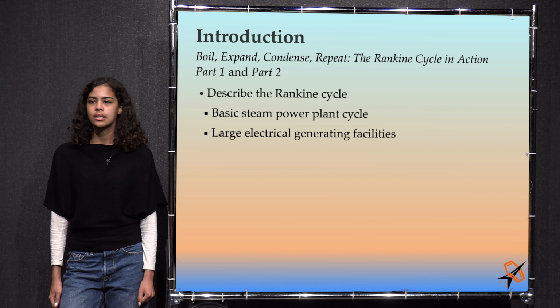We have a boiler, a turbine, a condenser, and a pump. On the Carnot steam cycle, we started at state B and did an isothermal transition in the boiler, an isentropic expansion in the two-phase region in the turbine, an isothermal condensation, and then an isentropic pumping or compression of the partially condensed steam to return to state B at the input to the boiler.